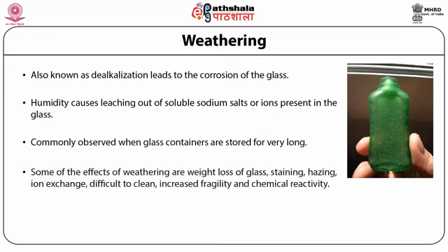Some of the effects of weathering are weight loss of the glass, staining, hazing, ion exchange, and difficulty in cleaning. It also increases fragility and chemical reactivity, and ultimately it will affect the quality of the product. So one should be very selective when using glass as a packaging material. Before selecting a glass, the formulator should know the quality or characteristics of the preparation which he or she is going to store in the glass.